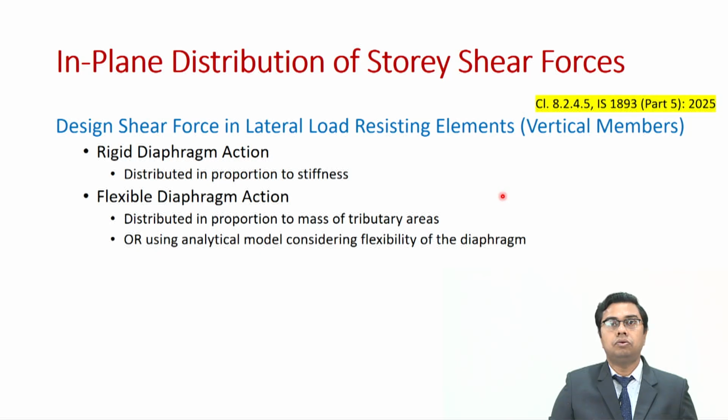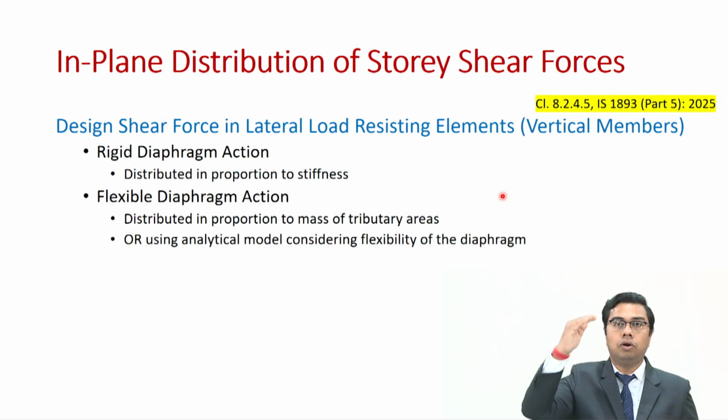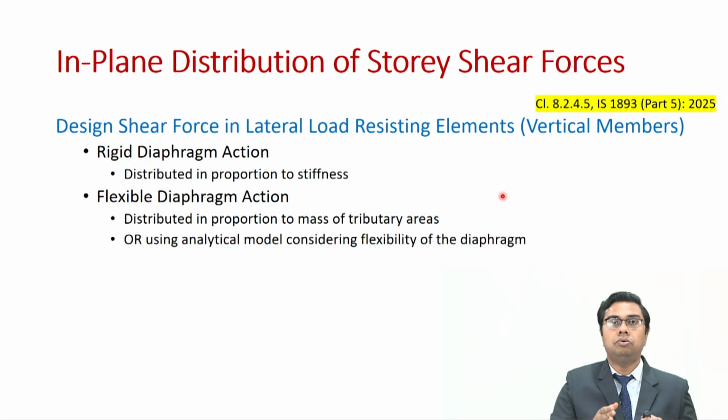So, in today's class we have learnt how to estimate the total design seismic load on a building using the equivalent static method, how to distribute it across different floor levels, and further how to distribute the story shear among different lateral load resisting elements. In the upcoming class, we will illustrate it through a worked out example.